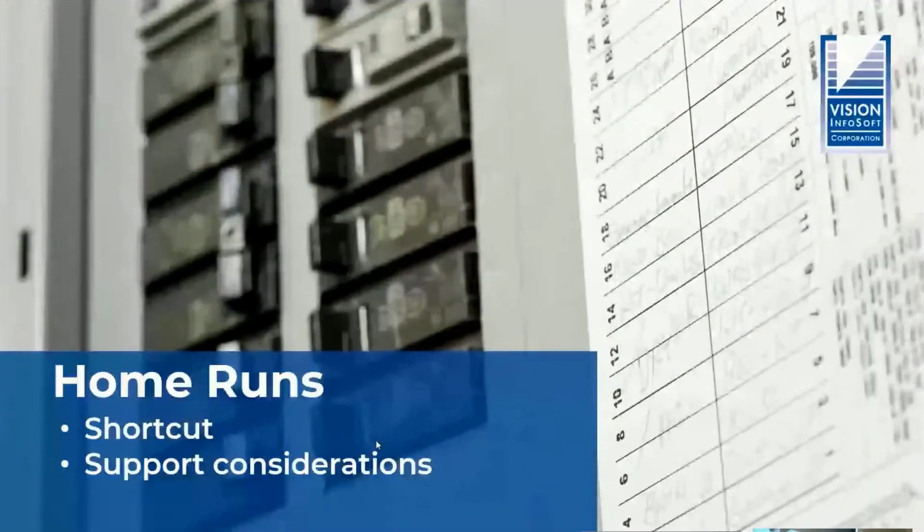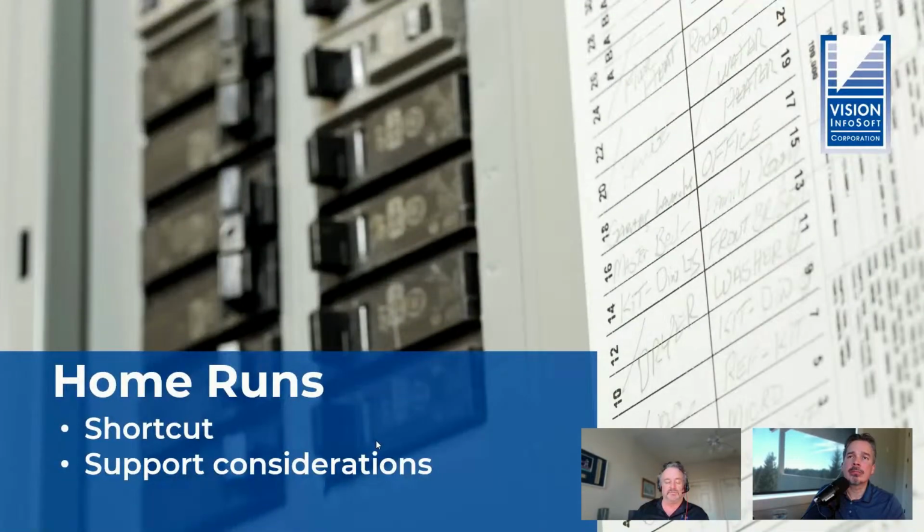In a home run, I typically put 7 number 12 wires, or if they're longer, I might put 7 number 10 wires. That'll give me my 3 circuits with my grounds and my neutrals and all that. And then all I need is the average distance of the home run. So you look at the building. Let's say the building is 100 feet wide and 50 feet the other direction. I typically take half of the longest dimension. So in this case it would be half of 100. Round it up a little bit.